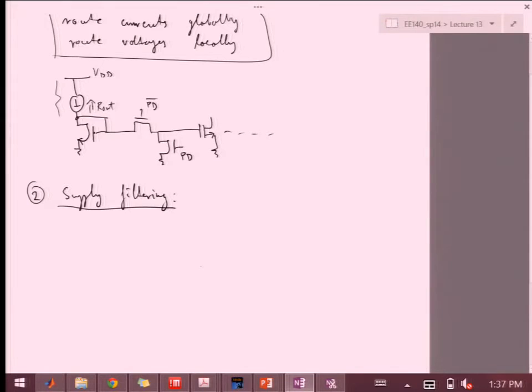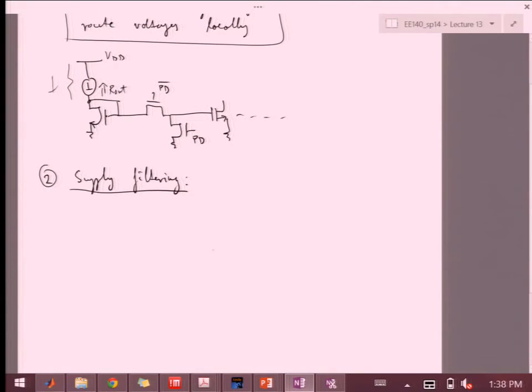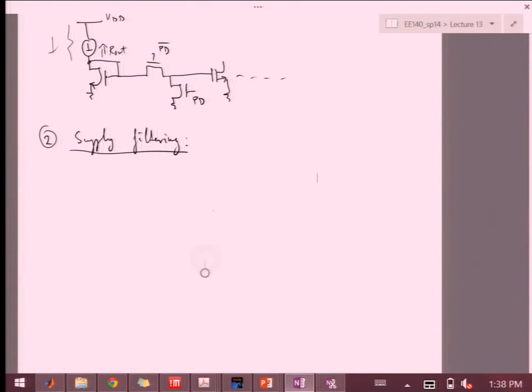In that case, whatever's happening on VDD is directly modulating whatever this current is. And we'll see in the next few foils some of the supply-dependent and independent biasings. But inevitably, whatever you do on the supply will kind of map into this reference current. And that will then map to the output. So if you want to filter that and get just the DC to replicate, but these supply noise or supply blips to not replicate, you can add some filtering.